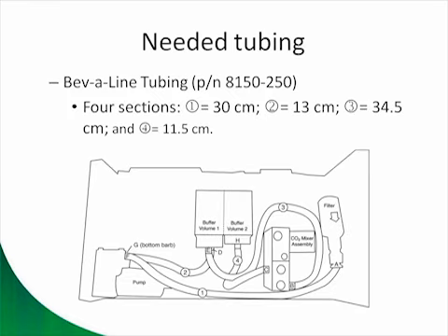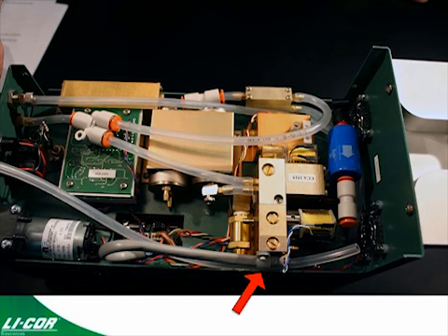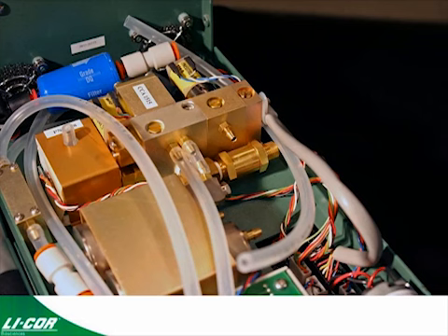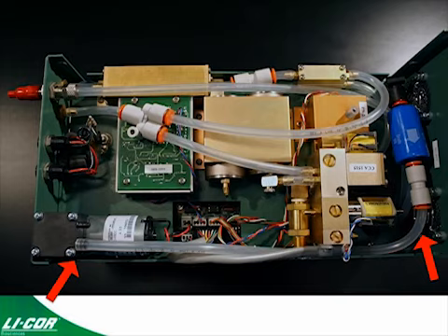The first thing that you want to do is slide the new tube number 1 under the cable clamp on the side of the CO2 mixer. This location will protect it from damage by the shell when you reinstall the shell on the carriage. Connect the end of the tube to the quick connect. Silicone or Teflon grease will make this connection easier. Push the tube in until the tube is firmly seated.